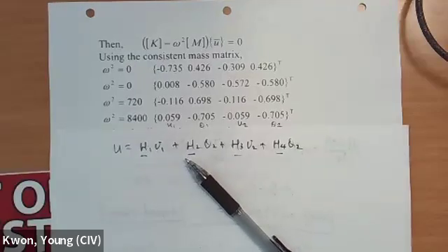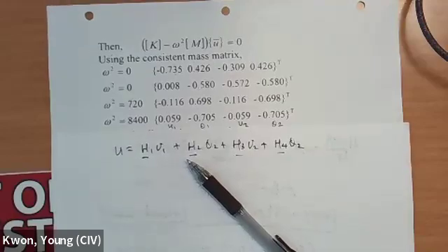I'm sure you have not seen zero eigenvalue in most applications because that's not our interest in most cases. But here, the zero eigenvalue makes sense. Why? What do you mean by zero eigenvalue? When you have rigid body motion, right? When you have a rigid body motion, then you are going to have zero eigenvalue. So rigid body motion does not have any vibration, just moving.